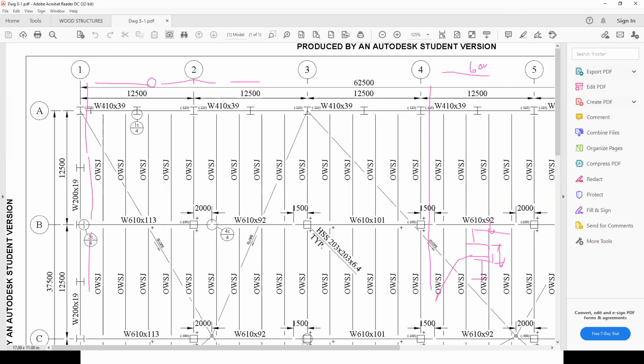That means that the top of this flange will be 100 millimeters below the elevation 6,000, and then this one here. So all of these beams here would be dropped by 100 in your case. This is 125, but like I said, this was a shoe for this joist. And if I'm not mistaken, if you go to the joist catalog, for the size of joist that we had, the manufacturer will tell you the size of the shoe. So the shoes are either 100 or 125. And therefore, in your case, this would be 100, not 125.